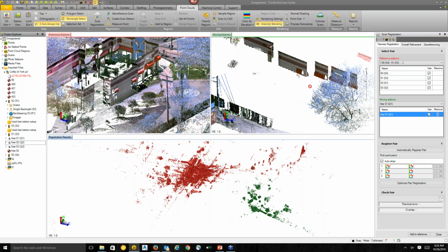We do have some flexibility. If you want to separate scans from what we call regular survey stations, then you can create a scan station from there, and you can create a duplicate point cloud, and that will allow you to move the point cloud belonging to a station setup that had a backside. But if it had a backside, if it was surveyed like an S7 or S6 or VX, in that case, you cannot register that data using the scan registration command.